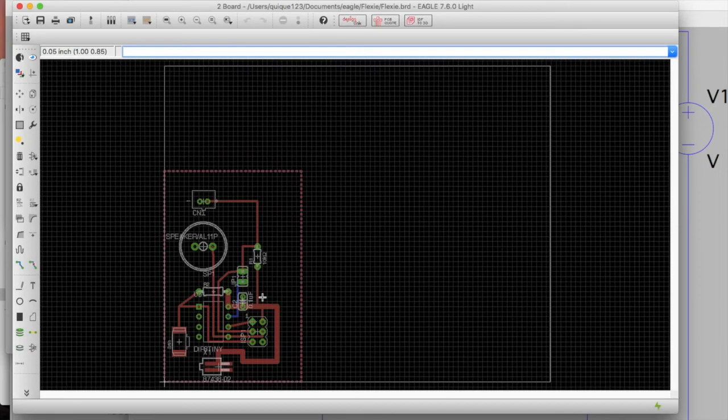There's way more detail than you can do in Fritzing. Remember that Fritzing also had that PCB tab. Well, here you can define the thickness of the traces. You can define not just the top layer, but the bottom layer, and even middle layers in between if you want to route connections on the inside of the board. And it's incredibly detailed, and it has a lot of helpful features to help you manually route and make connections and leave spacing. It's a very, very, very powerful package.